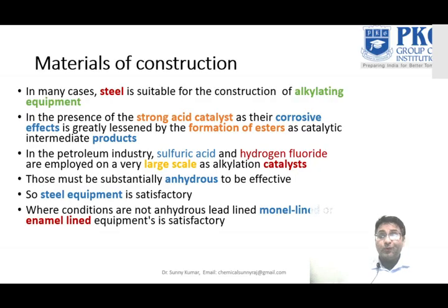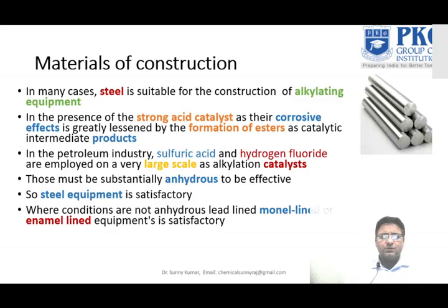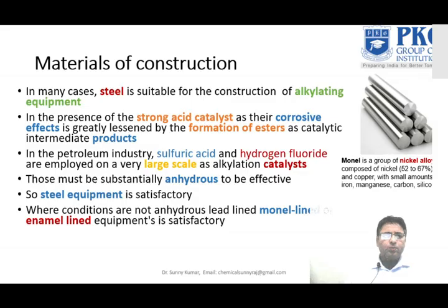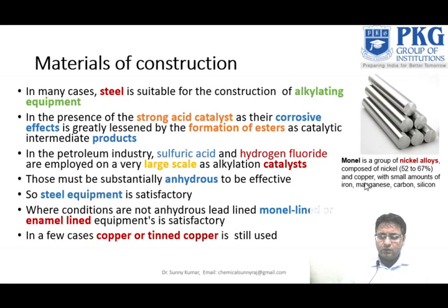So what are monel lining and enamel lining? We will discuss them now. This monel material is a group of nickel alloys composed of nickel and copper with small amounts of iron, manganese, carbon and silicon.